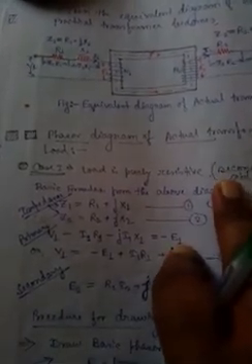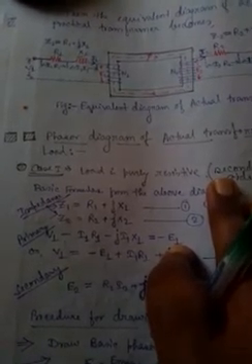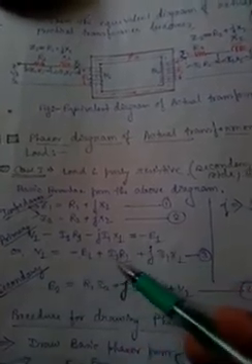That's why this difference equals minus E1. If there is no load, that means the ideal condition, and the resistive drop and reactive drop are not there. In that case, V1 will be equal to minus E1. So automatically V1 will be equal to minus E1 plus I1 R1 plus jI1 X1.